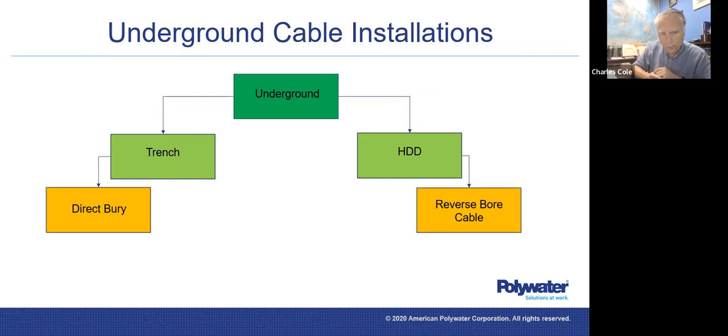So from an open trench, you can direct bury. That doesn't involve duct, nor does reverse bore cable. You're boring using HDD technology, and then once you get to the end, you're attaching the cable to the HDD bore and pulling that back through. So that's not going through duct either. So let's go to the next click here.